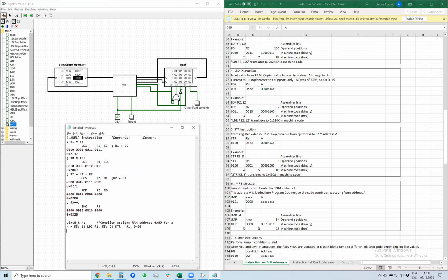Because microcontrollers, to be cheap, have to be made really simple. This is why there isn't such an instruction that could take a number from program memory and put it directly into random access memory. It would need so many select signals for address selection, RAM, and so on, that processors would be very big and complicated.